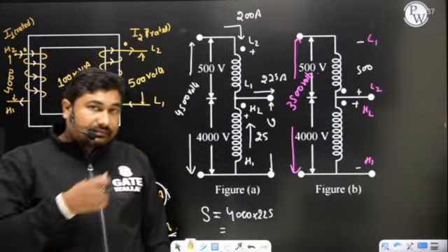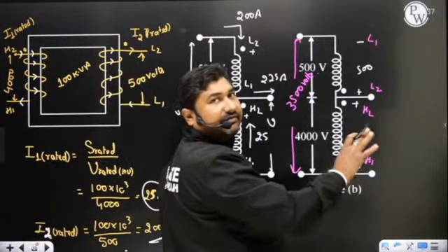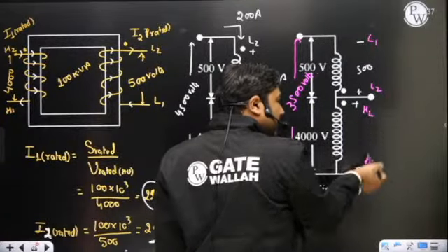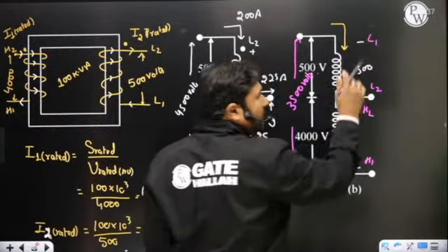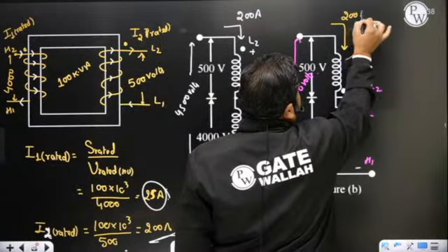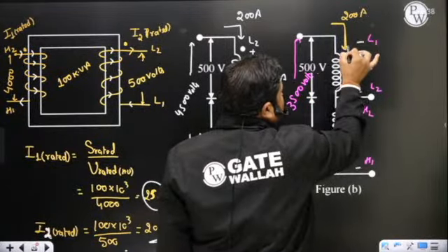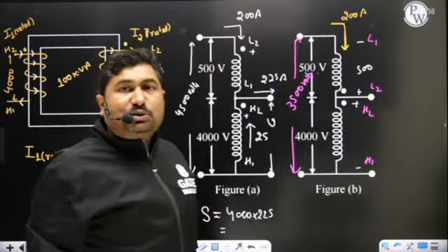Yes, sir. So, sir, we can take any condition reference. Yes, either you can start from H2 H1 or from L2 L1. Let us take this as a current. You can take any reference. So let us take this as a current. Maximum current that can flow is 200 ampere. This current is leaving through dot. Please observe, this current is leaving the winding L1 L2 through dot.